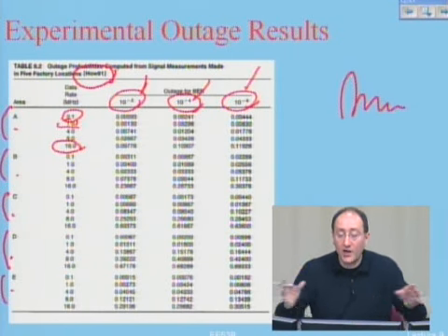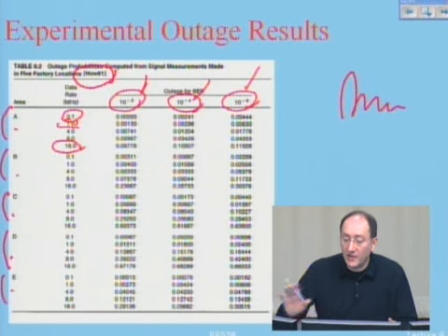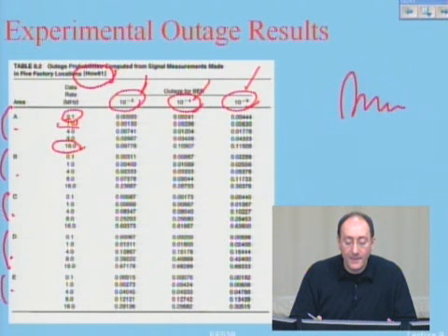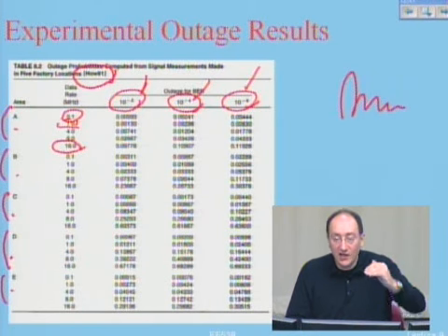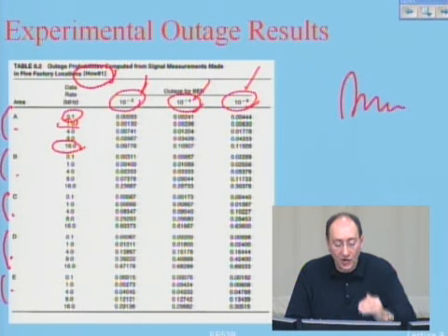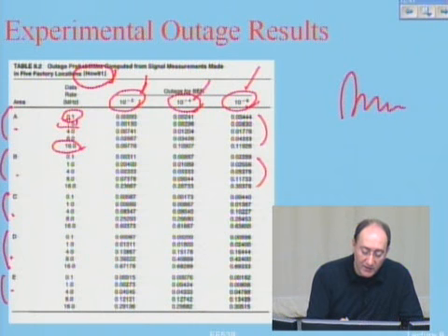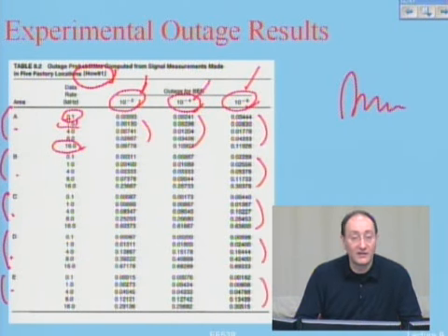So say I have 100 channel impulse responses. I calculate the error rate for all of them. Then I see in how many places I'm worse than 10 to the minus 2, how many places I'm worse than 10 to the minus 4, and how many places I'm worse than 10 to the minus 8. That's how he calculates these numbers, and he creates this table for different areas.